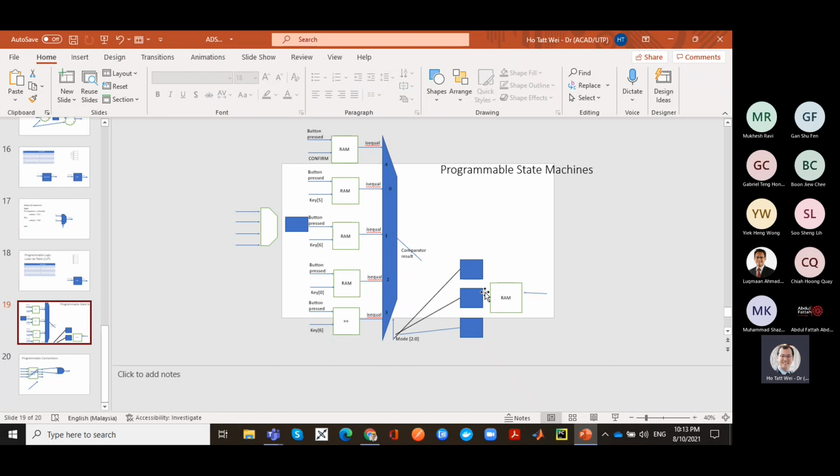That means this same hardware, you are using it for different configurations of inputs at time 1, time 2, time 3, time 4. Whereas if you were to replicate this same hardware for each of those cases you want, you have 6 times more hardware or 8 times more hardware, but you get your results all in one time epoch, right? But if you're reusing that hardware, you have to reconfigure or reconnect it, change it, but you take longer time, right? So programmability allows you to trade off resources or space with time, okay?